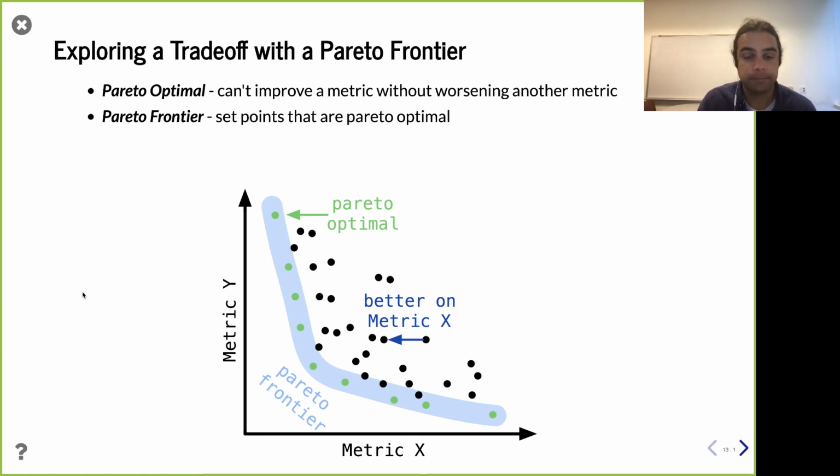Naturally, the really fast designs might take more power, and the really slow designs might take less power, so it's a trade-off. You go faster or you use more power. So how do you explore that? Of all the possible hardware designs, especially with all your various parameters plugged into your generators, there's actually a lot of design points, right?